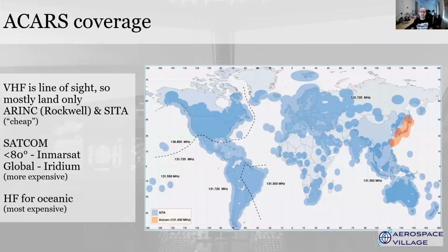So as we've said, the original plain old ACARS and ACARS over AVLC use VHF radios, so need direct line of sight, and that includes the Earth being round, of course, to a ground station. Aircraft are often flying pretty high up, 35,000 feet or more, so actually the range of a single transmitter is still quite large. But you can see from SITA's coverage map here, there are lots of gaps over oceans, Africa, and places aircraft tend not to fly very much, like northern Canada.